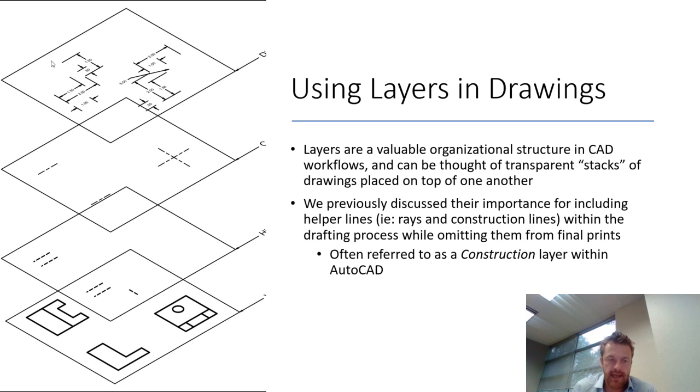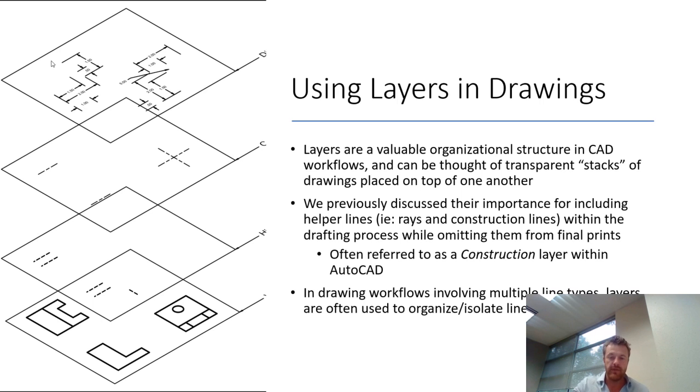The one thing I would say is that in most engineering drawings, since there's such a push towards standardization throughout engineering in order to be efficient, those names are oftentimes common. Not all the time and not across organizations, but don't be surprised if you see a common layering structure with the names and line styles consistent across various drawings. So going back, it's not surprising to see a construction layer where all of your helper lines that we just spoke of would be included.